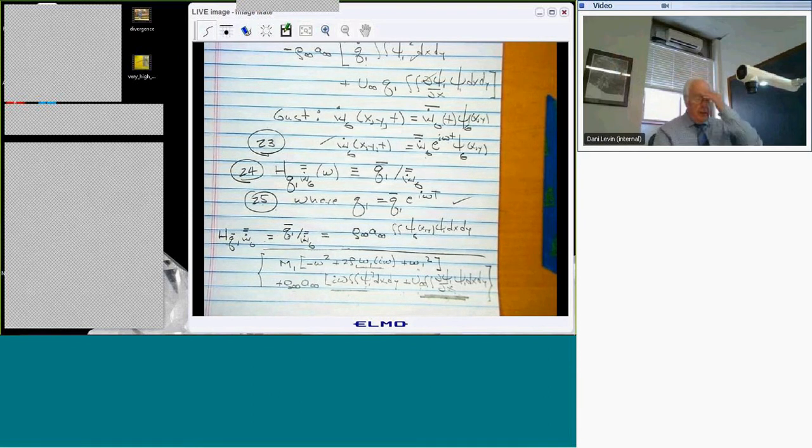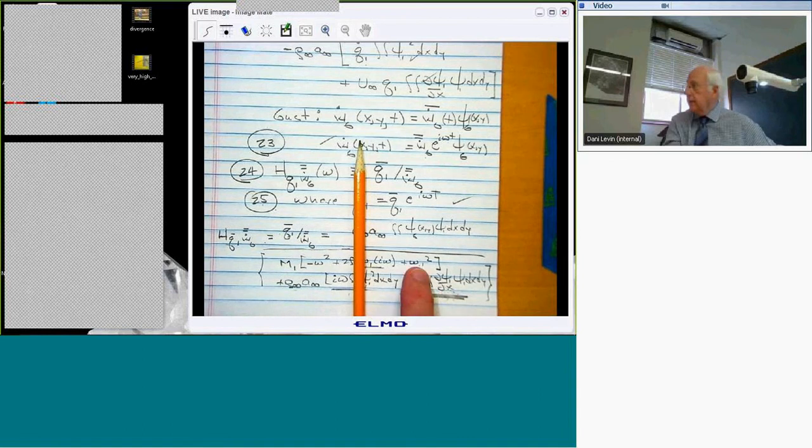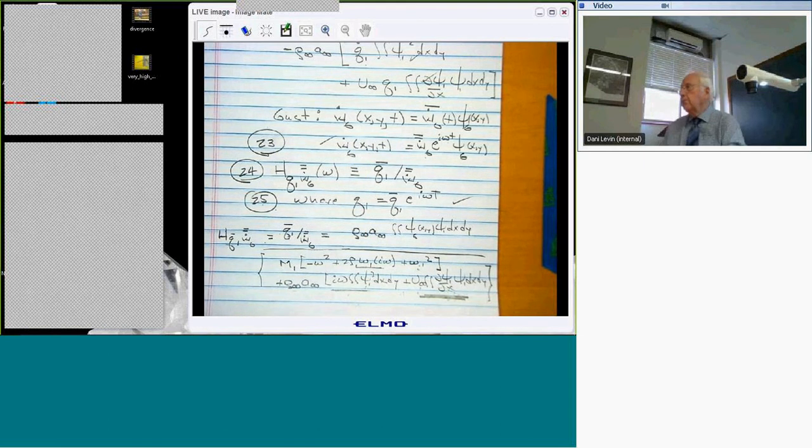Okay. Now, having said that, there is the possibility of another kind of instability, not flutter, but another kind of instability we talked about earlier in this course, due to this term. Look at this term and this term. Forget about the damping for the moment, right? Look at these two terms. If this term is negative, it can cancel out that term. And when that happens, the total coefficient, which doesn't depend on frequency, is negative. And what kind of an instability would that be, he asked? Divergence. It's a loss of stiffness.